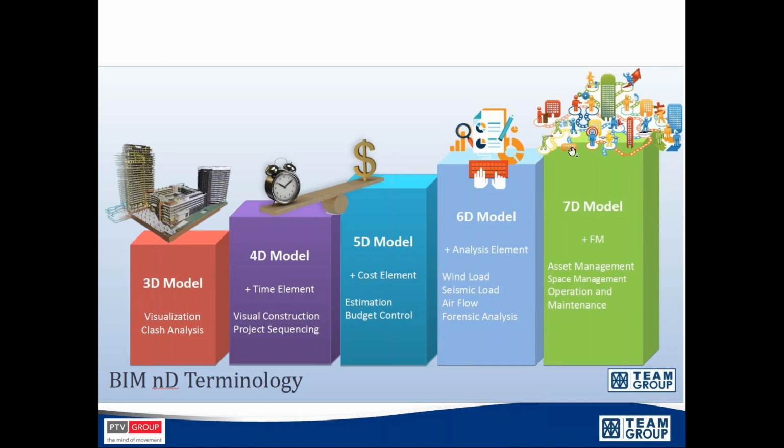And other than 3D, what else that BIM could do? Okay, 3D, we would talk about visualization or some crash analysis, some constructability analysis. And for 4D is something like you add time element to the 3D model, so you can visualize construction sequencing, construction scheduling, construction method. And when you add the cost element, BIM would become 5D.